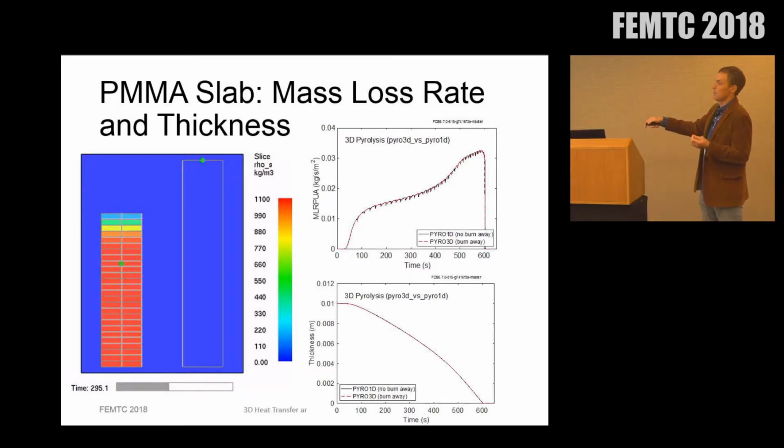We have to count the number of cells, multiply by its DZ, okay? To get this to look so smooth, even in these cells, I'm not only saying DZ times, and counting this is DZ times the cell volume ratio, right? And so that's something that we output. When you consider the cell volume ratio, you get something that is right on top of the 1D model. We wouldn't be able to get this close to the 1D model if we weren't also using the 1D kinetics model.